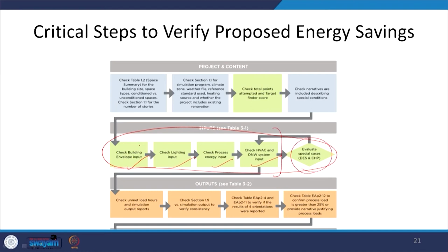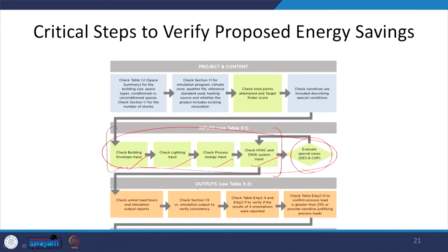Once the inputs have been sufficiently given, based upon what the proposed building is, and for the base case coming from the standards, we will then check the outputs. The outputs for unmet hours or simulation output reports, for verifying the consistency from its orientation point of view and its process load point of view. So, the outputs will be used to verify the inputs as well as the outputs.